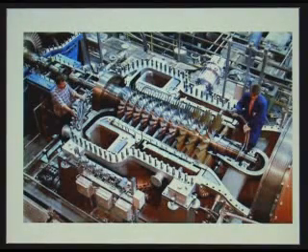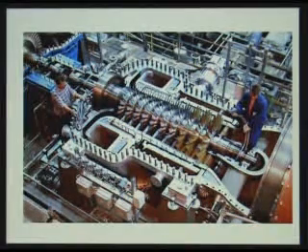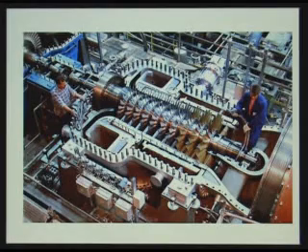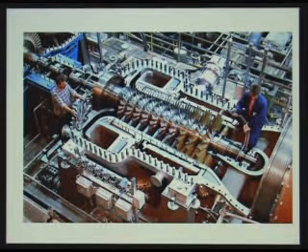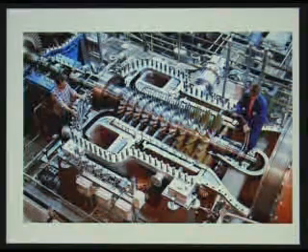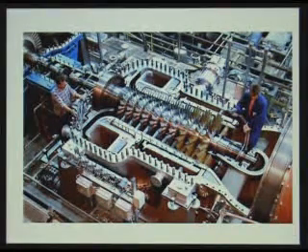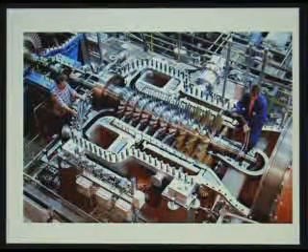Lots of aerodynamic blades spinning at a high speed. What they do is they impart, again, velocity to the gas stream, but instead of sending it out radially, they send it back axially. There's a stationary blade, which then does a conversion of the velocity, and it has a pressure rise across it, and also aligns it so that it's ready to be compressed by the next rotational section.